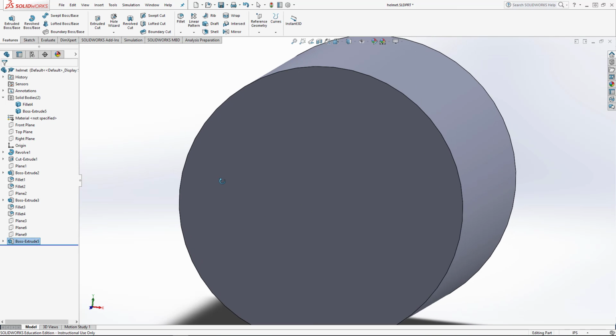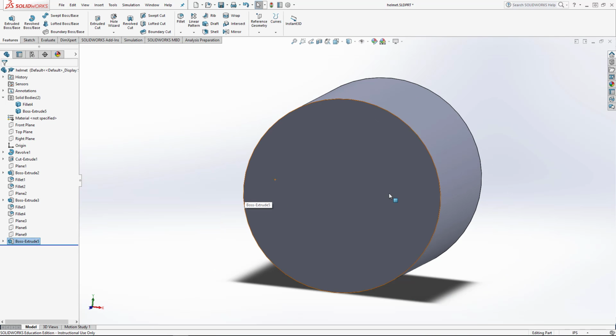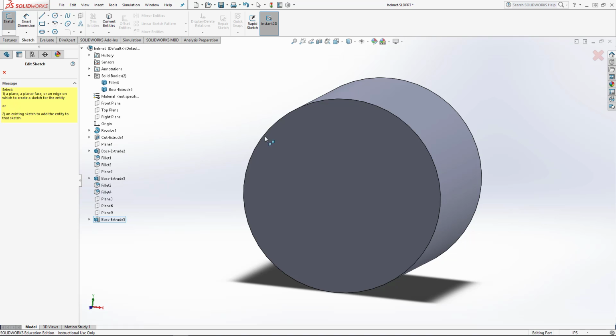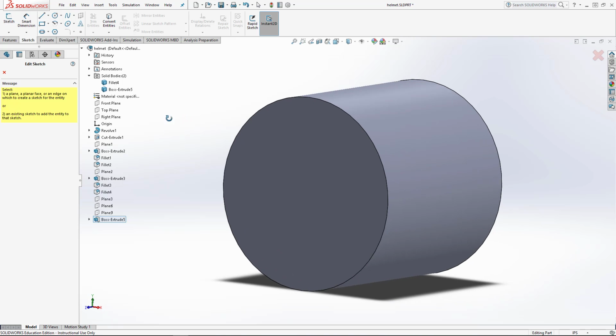All right, so they're both there. You can't really see it because of the cylinder. Now what we want to do, because of symmetry, is cut this in half. Now if you don't have symmetry, you can skip to the next step. But if you have symmetry, it's going to be helpful to see what's going on. Again, if you don't have symmetry, it's fine. It'll still work with the next step. All right, so I want to cut this thing in half.